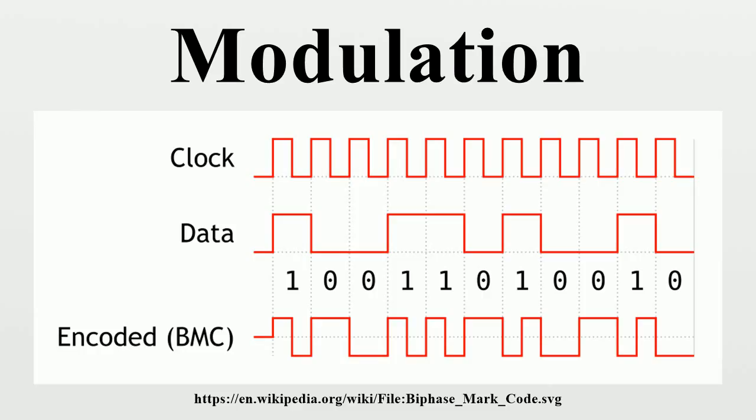Of the two kinds of RF power amplifier, switching amplifiers cost less and use less battery power than linear amplifiers of the same output power. However, they only work with relatively constant amplitude modulation signals such as angle modulation and CDMA, but not with QAM and OFDM. Nevertheless, even though switching amplifiers are completely unsuitable for normal QAM constellations, often the QAM modulation principles are used to drive switching amplifiers with these FM and other waveforms. And sometimes QAM demodulators are used to receive the signals put out by these switching amplifiers.